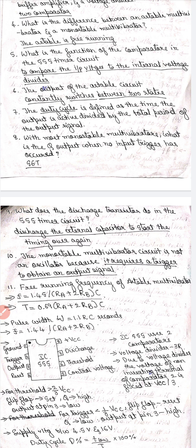What does the discharge transistor do in the 555 timer? It will discharge the external capacitor to start the timing over again.